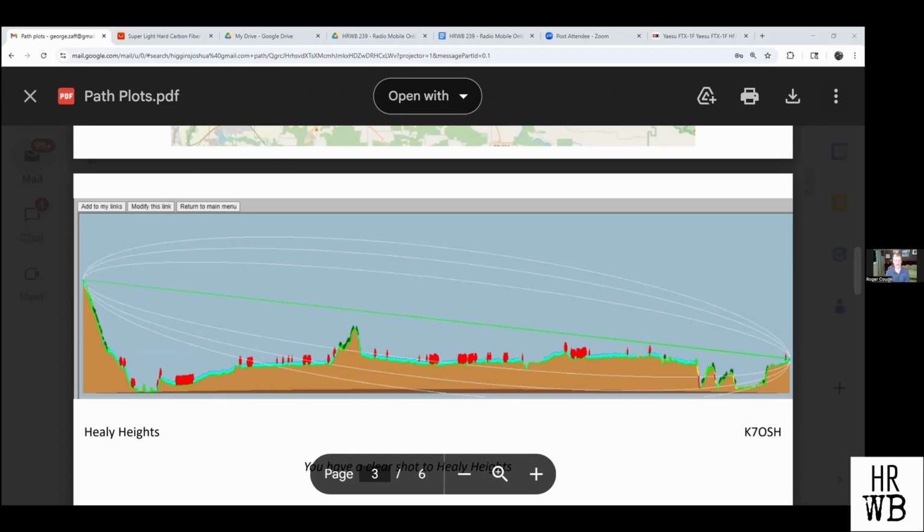Another example is those amateurs who do balloon launch. If you send a balloon and you listen to the signal, you have most of the time clearance, a lot of clearance. And suddenly the signal goes up and down. So it depends on those Fresnel zones that become in phase or out of phase, in phase, out of phase.